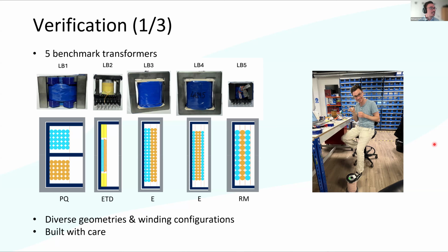Good. And I think it's also always been a topic that people like to look at the leakage as a percentage of the magnetizing inductance. Now, my experience is that you can gap the core and then still get almost the same leakage inductance. So in the end, this percentage figure is not that much a figure of merit for me. Can you comment on what the impact of the gap on the leakage inductance is?